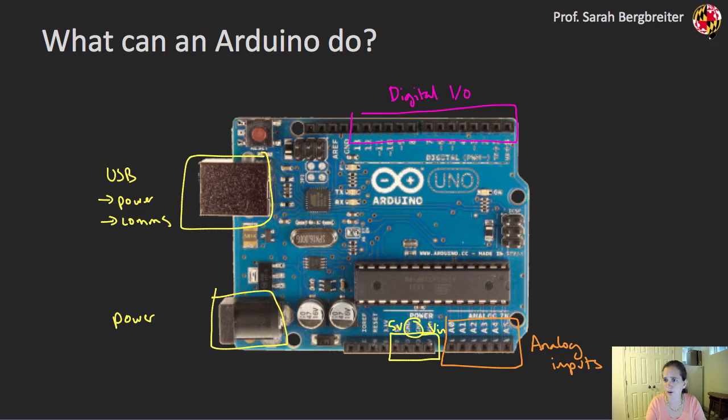And I have a number of other cool things that I can look at. I have an LED right here, and that LED can be useful for a lot of different things, telling me that I'm actually seeing things correctly or not. I have these little marks right here, for example. These are what we call PWM outputs, and I can think of these as a pseudo analog output.